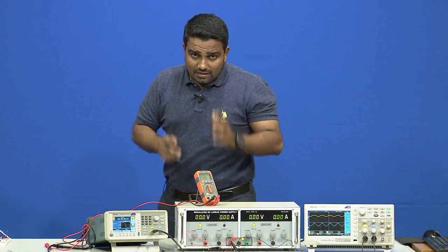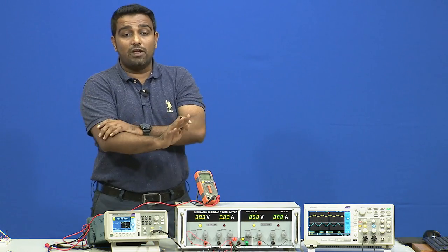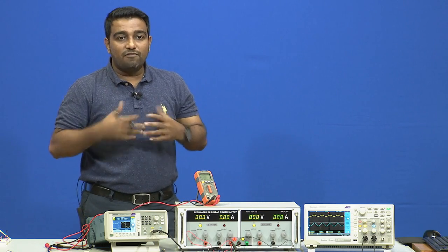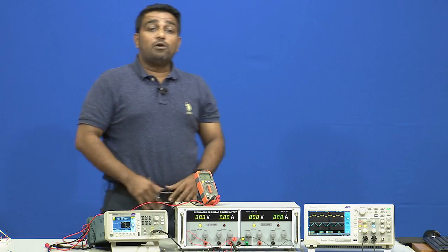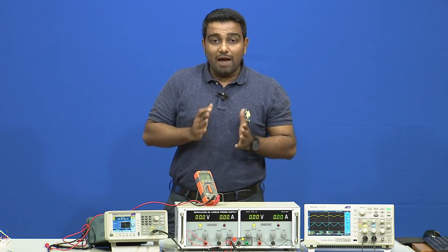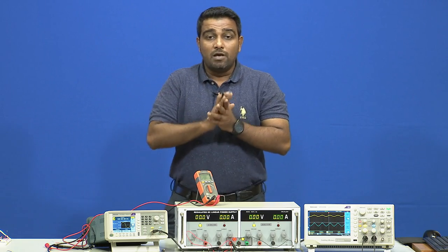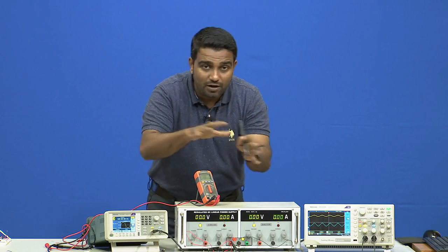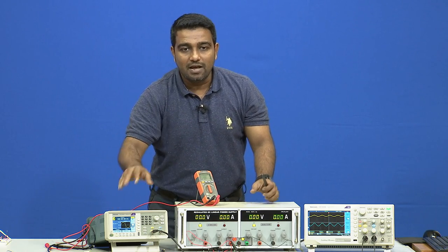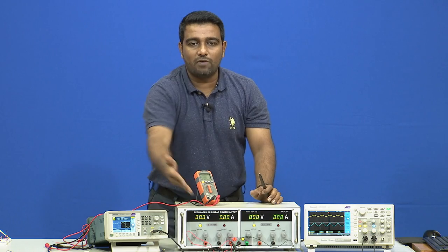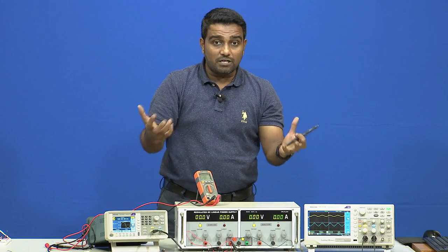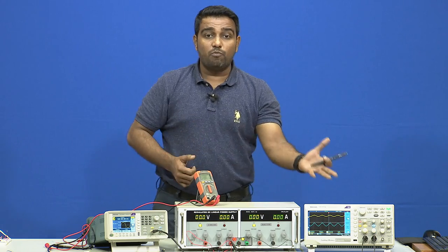Like I said, it is absolutely okay when you are trying experiments on the breadboard and trying different circuits, and you are not able to get the answer you are expecting. What we have to do is understand what the problem was. Here, in this particular experiment, there was no problem with the circuit, it was a problem with the input signal, right. The input signal given to the circuit was a square wave, and we were under the impression that the input is a sine wave and wondering why the output is a square wave.